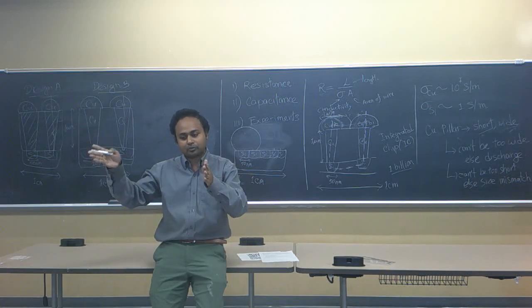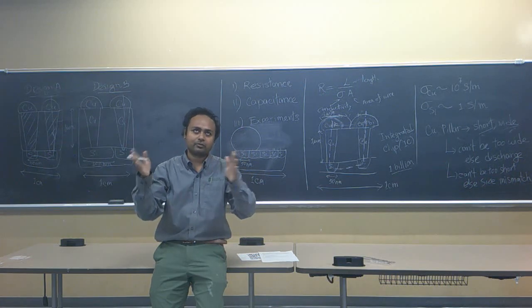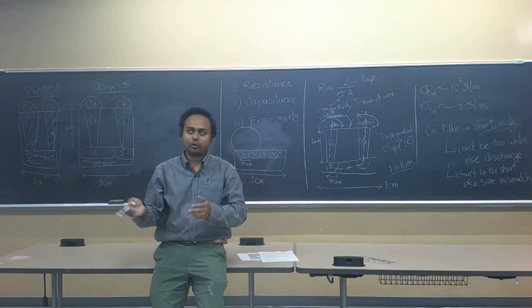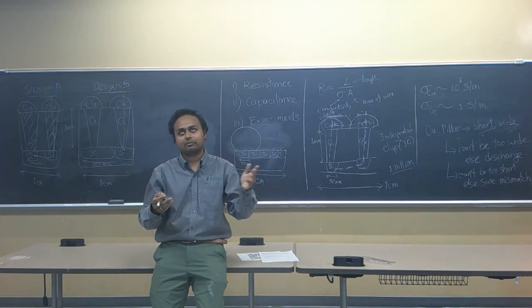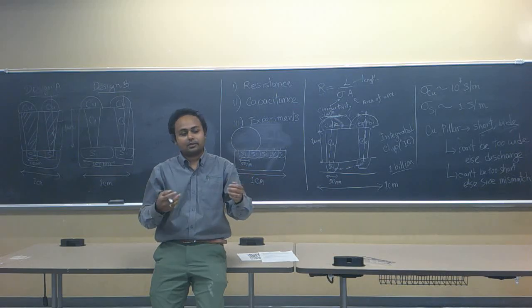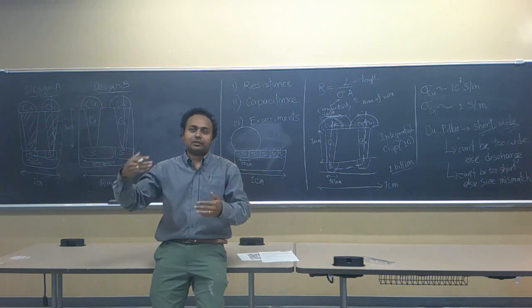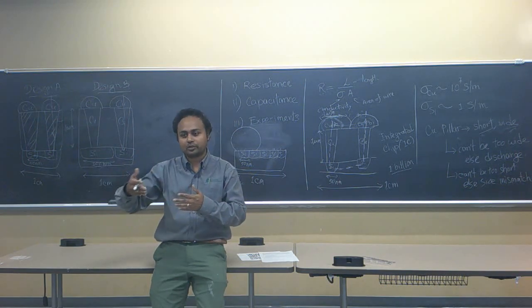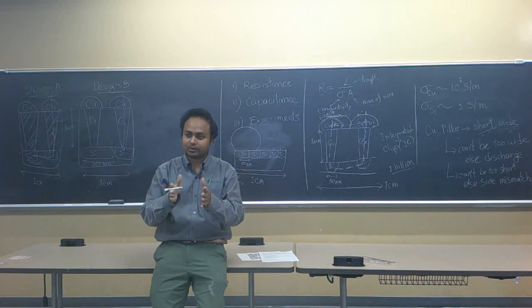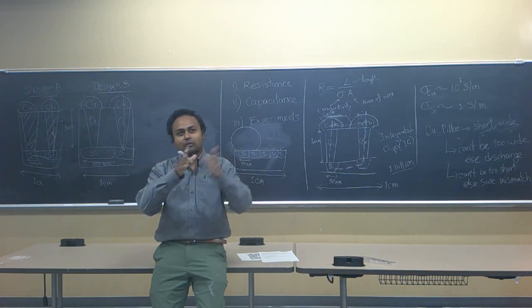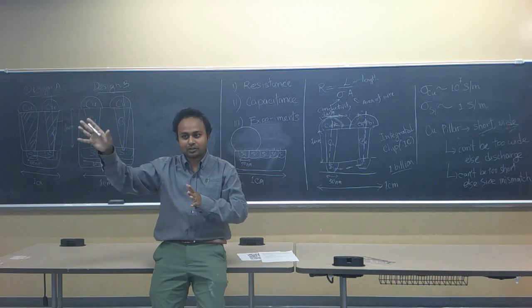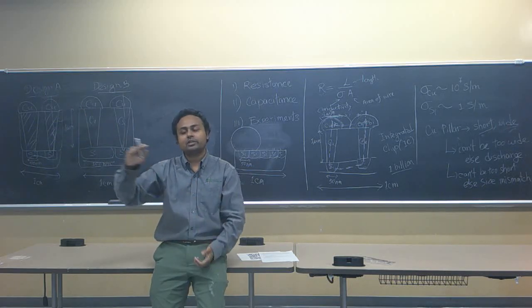And then from 1 micron, we went to 500 nanometer, then probably 180 nanometer, then 65 nanometer, then 32 nanometer, 22 nanometer. So every year or every 2 years, we shrunk down the chip. However, we only maintained the actual physical size versus the process node name 1:1 until we reached 45 nanometer.